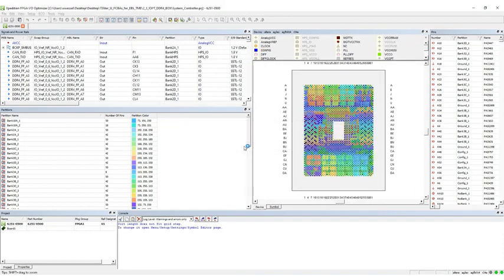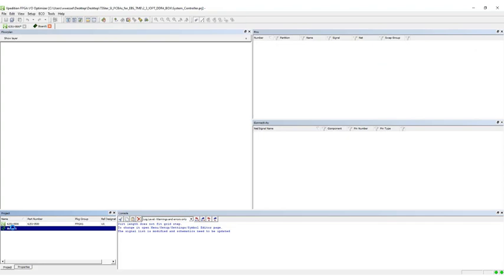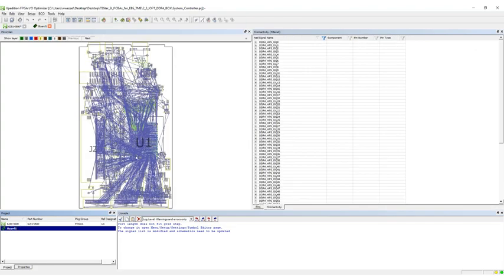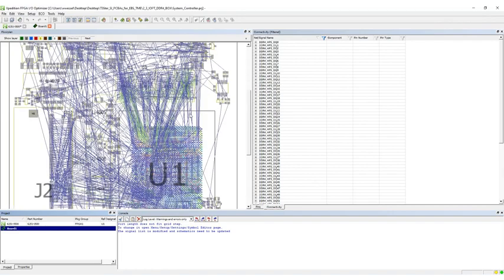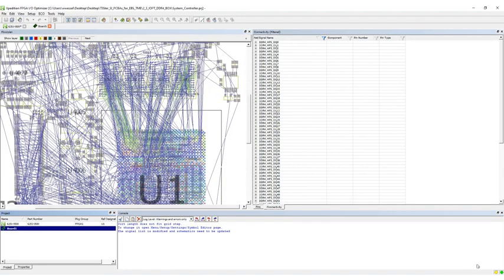The main advantages of the integrated I/O optimization are that it knows all the FPGA vendor rules for pin assignment and swapping, and that it is PCB aware. The floor plan view represents the current state of the PCB layout and allows the user to filter for nets and layers. On top of these, the placement can be adjusted here, and the changes are sent back to Expedition